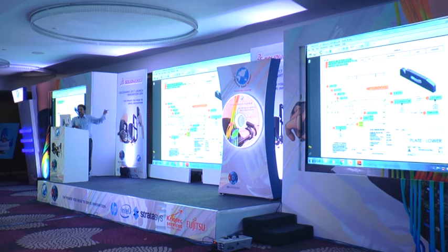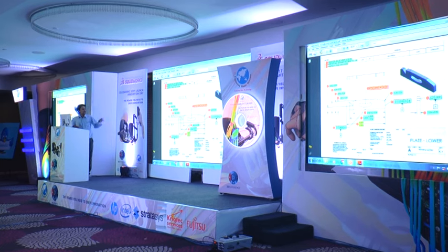So all the notes, dimensions and GD&Ts, you can see all have a balloon, and also color coding will be available for it. If it is within the limit, it will show in green. If it is out of the limit, it will show in red, and if it is marginal, it will show in yellow. So the final output of the drawing will be like this,